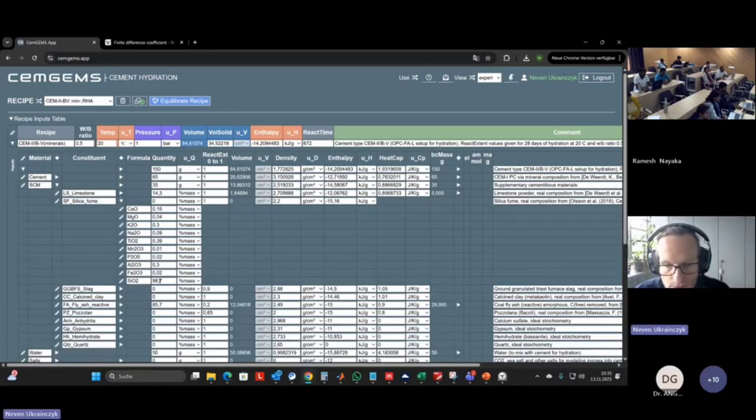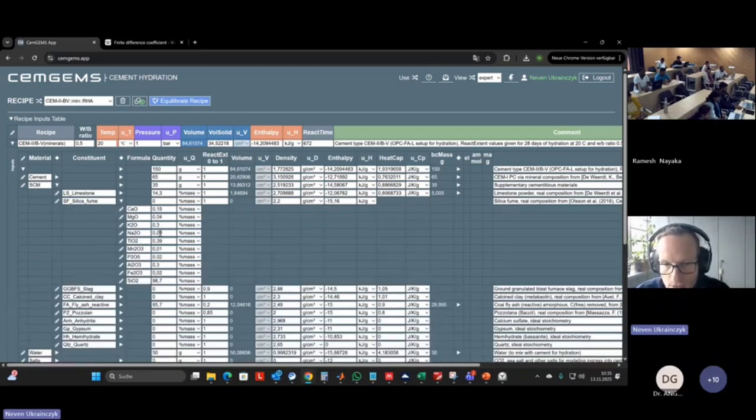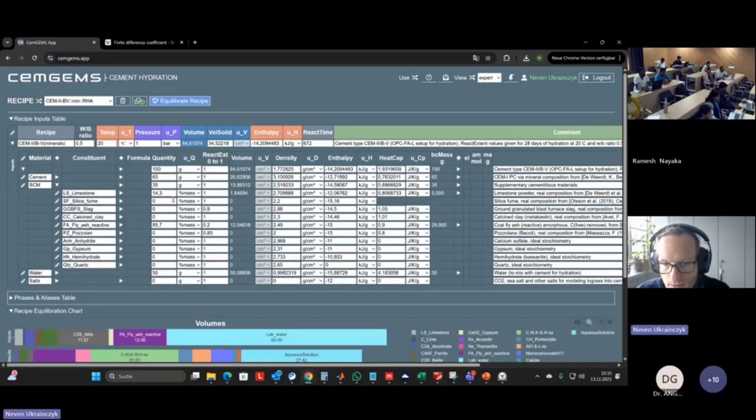I think the composition is mostly silica. This is also maybe a little bit lower for rice husk ash, but it doesn't matter. You know now where to change it. So you should change this composition. You can rename here rice husk ash. And we can say, I don't know how much you want inside. How much do you usually put? Probably 10%.